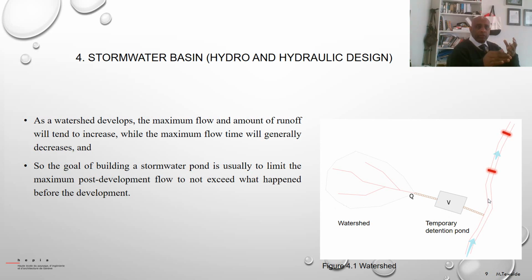The structures that are already constructed for a certain peak discharge are affected when the peak now increases. That structure may be unusable, for example. If there is a culvert, for example, the discharge might overtop the culvert, you see. So there is a lot of damage at the downstream side of the river because of the increase of the runoff. That is one case.